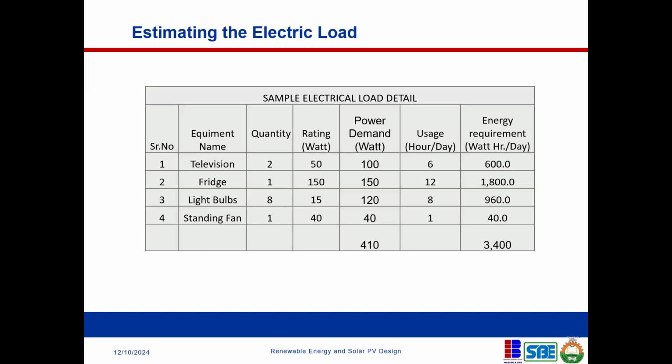But in this case, it's not as intense as an industrial energy audit like we did in our first batch of the training. But it's also very important that you understand the load, look at the TV systems and see what energy efficient upgrade you can recommend. If they intend to power an air conditioning system, it might be recommended to go for an inverter type air conditioning system if budget allows, because I know those kinds of appliances are a little bit more expensive than the conventional appliances. However, over time, it's going to be cheaper because they're going to save a lot of money by using those appliances over time, and then make up the gap in the cost of purchasing the equipment.